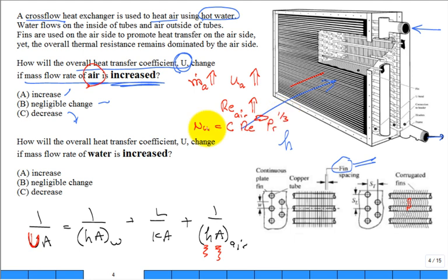Okay, so embedded in the Nusselt number is my h. So it's hL divided by k equals a constant, Reynolds number based on L, and our Reynolds number is rho U L divided by mu. And then the Prandtl to the 1/3. And I left off that exponent. Now, if it's external flow, a lot of those correlations had an exponent of 1/2. If it was internal, Dittus-Boelter, who can remember in the Dittus-Boelter, Reynolds number to what power?